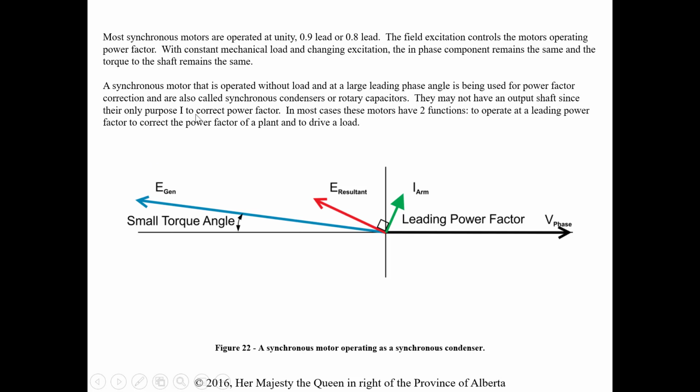The field excitation controls the motor's operating power factor. With a constant mechanical load and changing the excitation, the in-phase component remains the same and the torque to the shaft remains the same. So I'm still able to drive the mechanical load, the wattage of that load.